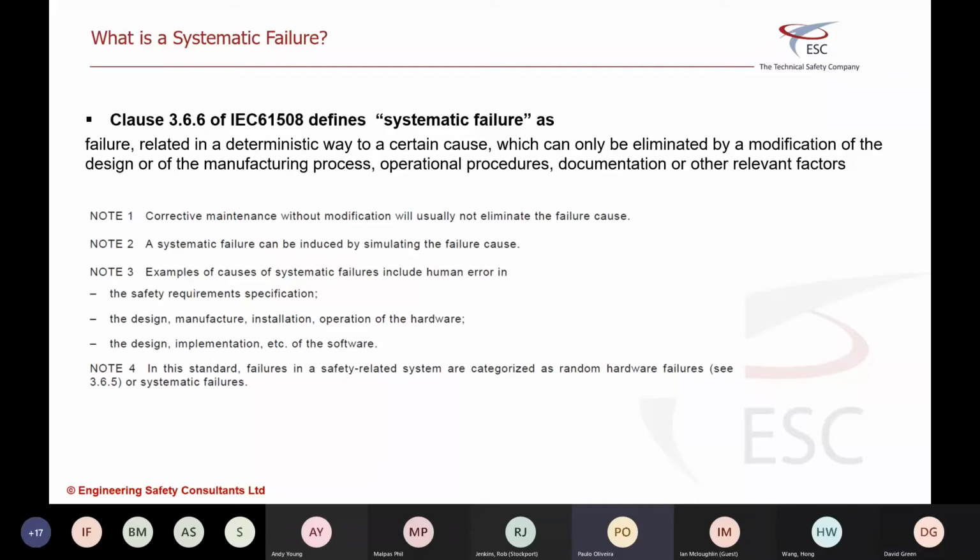During the planning of the installation and commissioning, there was an installation plan and the cable tag was 1, 2, 3, 4, and someone put the wrong tag on the wrong cable. When you tested that cable, you confirmed the functionality of that cable, but it's connected to the wrong thing. We need to find a way to confirm that that error is not going to carry into the operational phase, because it might have actually defeated the system from responding the way you expected it.